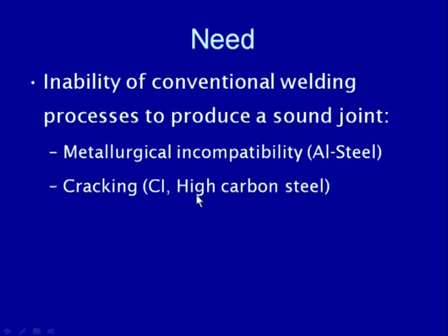There are certain metal systems which are very crack sensitive on heating followed by rapid cooling during conventional welding, and those metal systems frequently lead to cracking. So, to avoid the cracking of metal systems like cast iron and high carbon steels, instead of the arc welding or fusion welding processes, this set of joining processes is used, which involves brazing, soldering and braze welding.